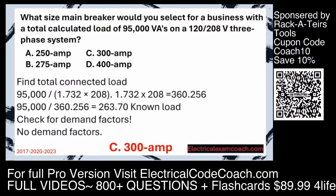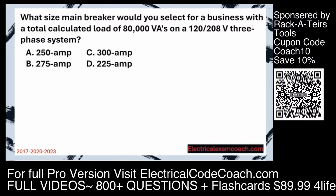The beauty of three-phase is the numbers come down. So this one's on a 300 amp service, which means we can put it on smaller wire, which might mean we can put it in smaller pipe, which might end up having a smaller overall cost. Let's get to it. What size main breaker would you select for a business with a total calculated load of 80,000 VAs on a 120/208 three-phase system?